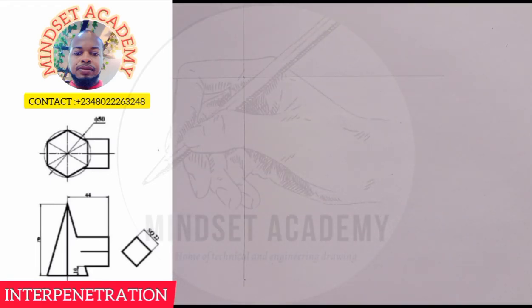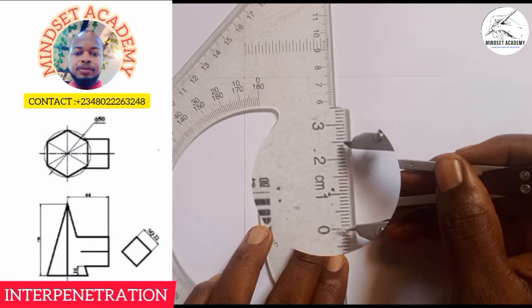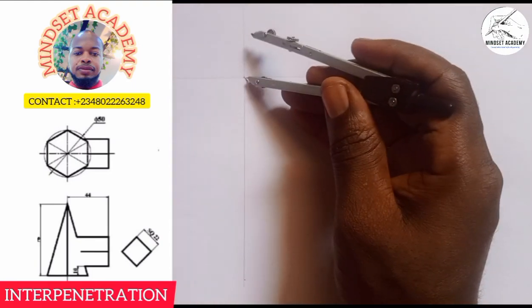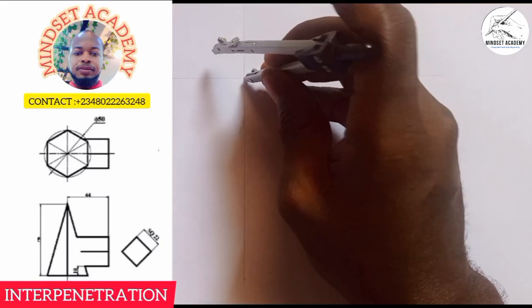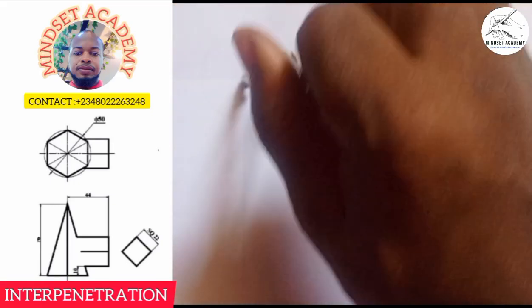Now we'll start with the plan first of all. From the plan, we have a hexagon. A hexagon has 6 sides, a regular hexagon, that's what we have there. That is the base of the pyramid, looking from the top. We're given a diameter of 50, so I am going to measure half of 50, which is 25, from 0 to 25, and place it here. This is where I'm going to draw my circle, with a faint line.